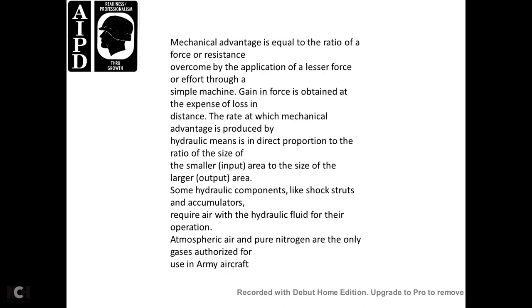Mechanical advantage is equal to the ratio of the force, or resistance, overcome to the application of a lesser force. Through a simple machine, the force is obtained at the expense of a loss of distance. In hydraulics, the mechanical advantage is the ratio of the size of the smaller input area to the size of the larger output area. Some hydraulic components like shock struts and accumulators require air along with hydraulic fluid for their operation.